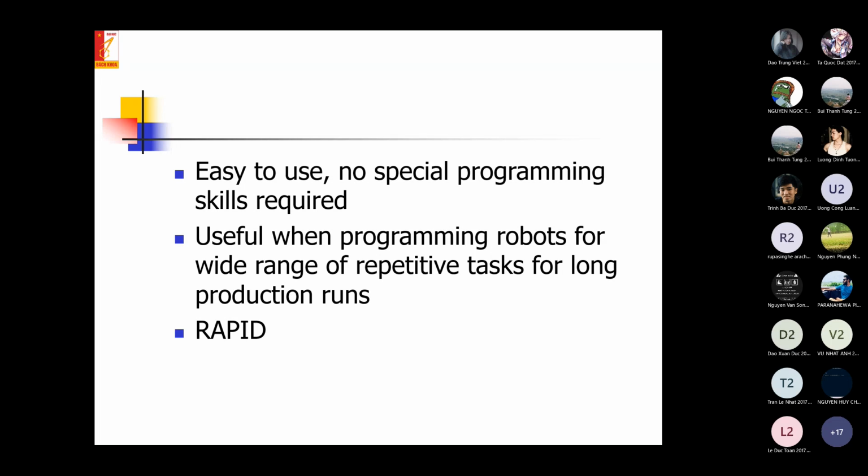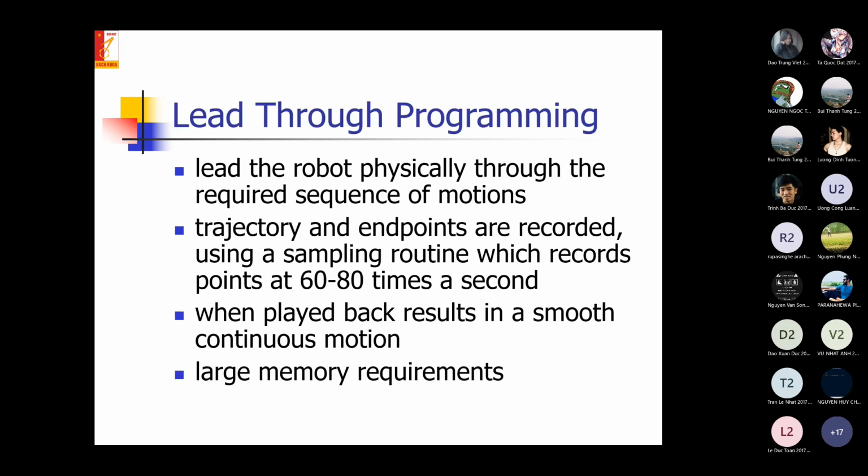So besides using the pendant, we can also use lead-through programming. For this, we can lead the robot physically through the required sequence of motions. Of course, by using the pendant, we can also teach some intermediate points.